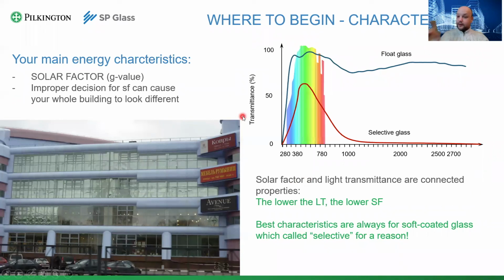So, solar factor. Another option. If you are advocating for a glass with a low solar factor, the thing is that if your building will have lower solar heat coming in, your spending on air conditioning equipment can also be lowered a lot, because obviously you need less powerful equipment to cool down the whole building if you have less heat coming in. That is also a point of consideration, and it can be presented to an owner or a design company as a bonus, as a benefit.